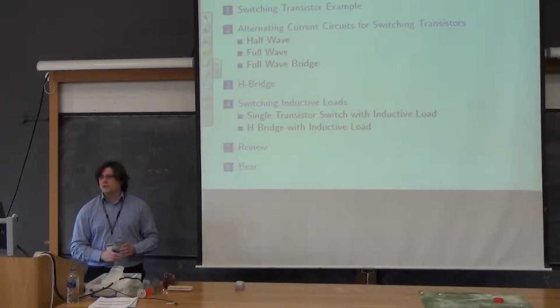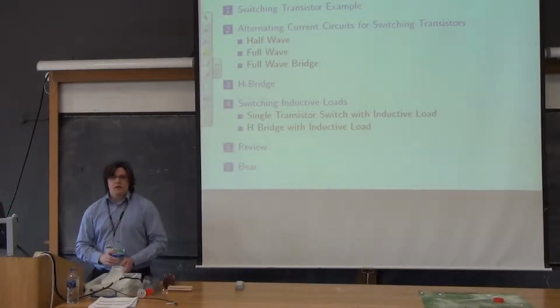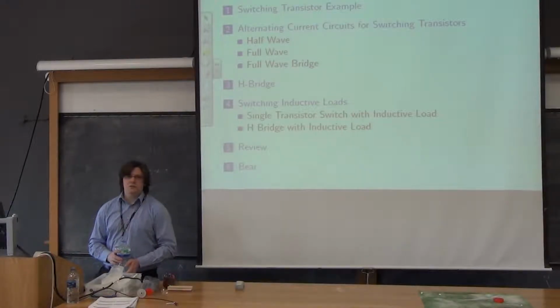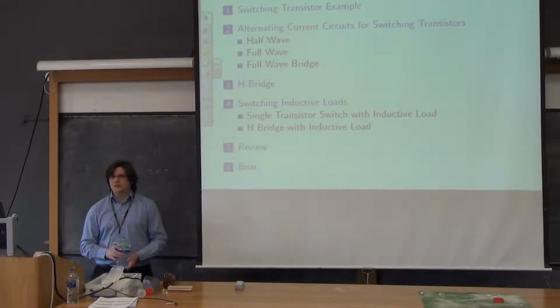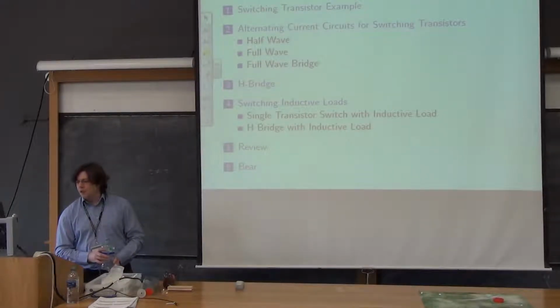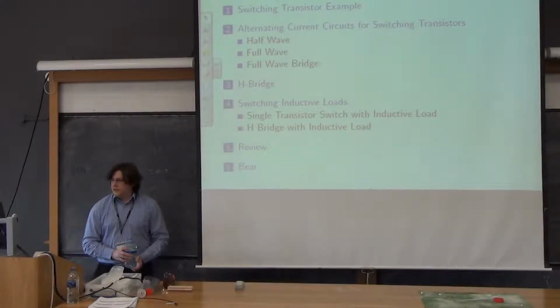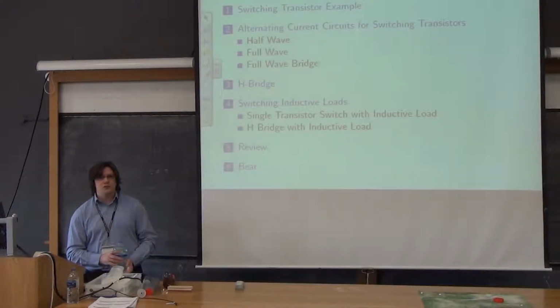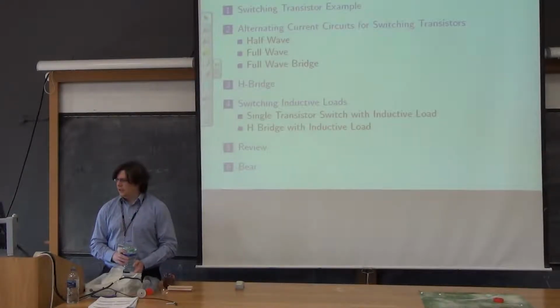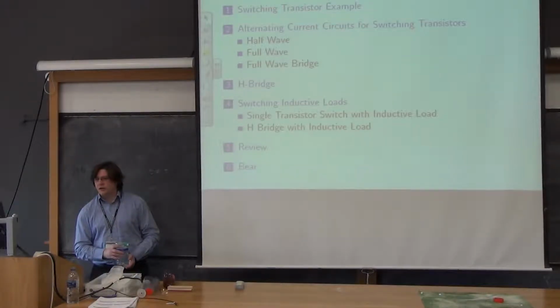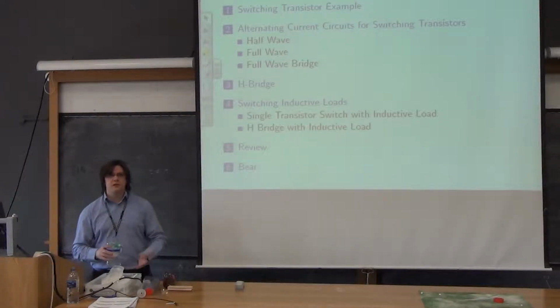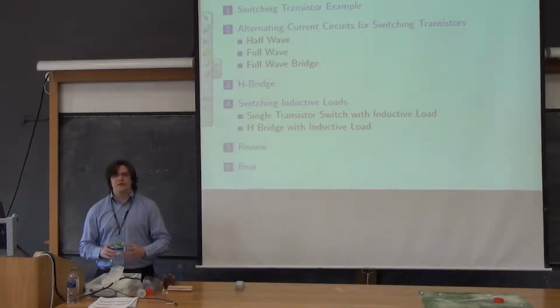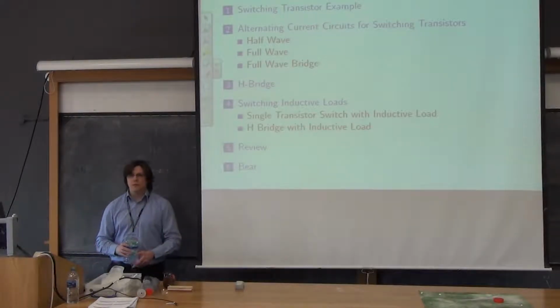So what happens if we want to do switching on circuits where we have sinusoidal signals? We could just use lots of transistors, but there are some cunning circuits we can use to get out of it. Then we'll discuss the H-bridge for a bit, which is a collection of 4 transistors that's often used to drive motors and generators. And then we'll round off this lecture by talking about how you switch inductive loads. That's to say, if you wanted to use a transistor to switch a relay or something similar, you'd have to worry about the energy that was stored in the relay coil and what happens to it,